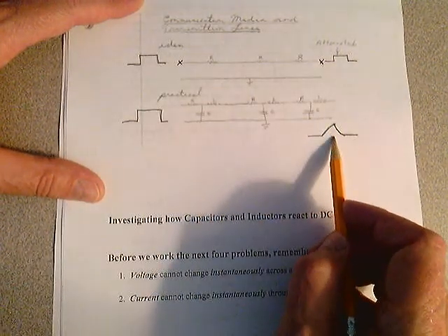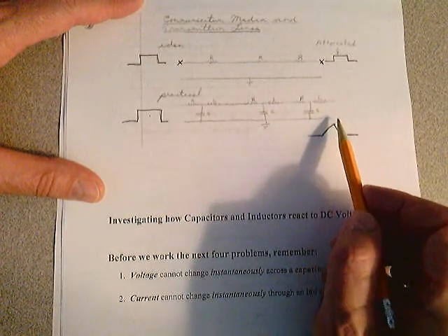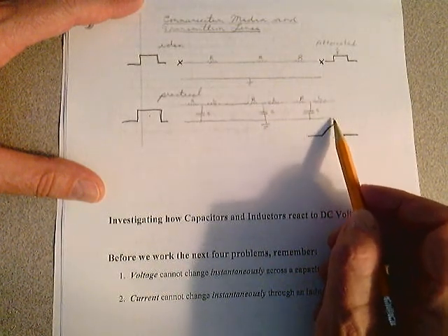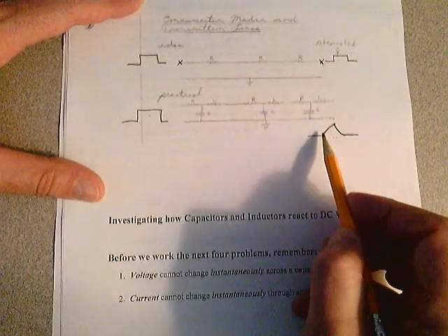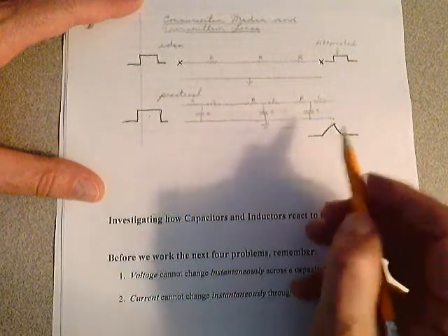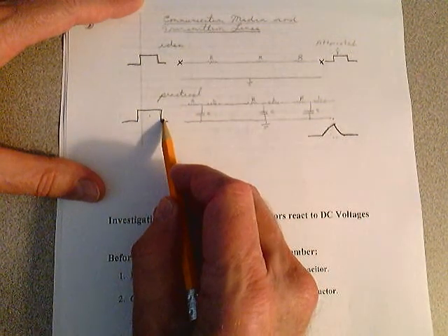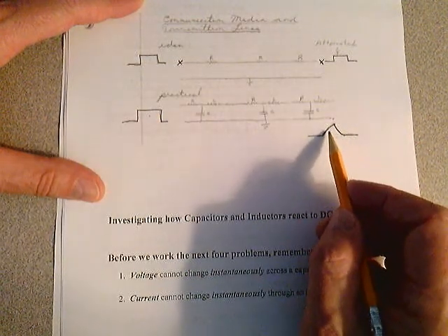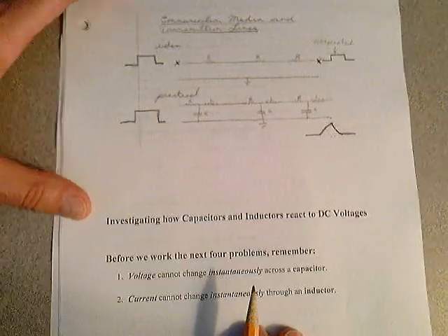So that's true attenuation of that signal. It gets beat down in magnitude because of that resistance, the loss in voltage distributed amongst the R's, and it gets a roundness, exponential shape to it on the rising edge and on the falling edge out here. And that's because of the capacitance and the inductance that's measured in that wire.